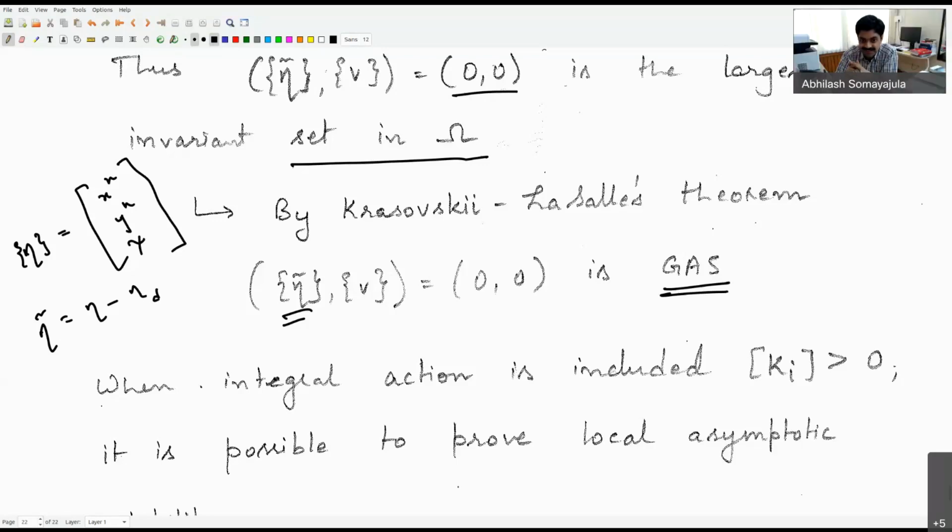Yes. And as I choose the desired point at different locations, as my waypoints are changing, it should now start tracking that new point, basically. Okay, it only goes to show that as long as the control law is chosen in this manner, the equilibrium point is stable enough. And it is globally asymptotically stable, so that if it starts at some other point, the craft will approach this point and orient itself into its correct orientation and stay there.